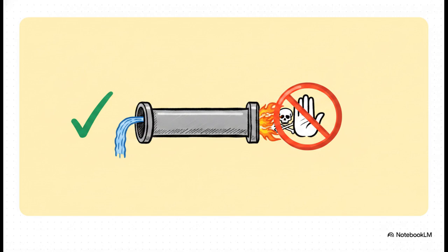Now, for Class C exchangers under C 1.61, that 150 psi limit stays, but the code explicitly states that cast iron shall not be used for lethal or flammable fluids at any pressure whatsoever. It's a complete absolute ban based entirely on safety.